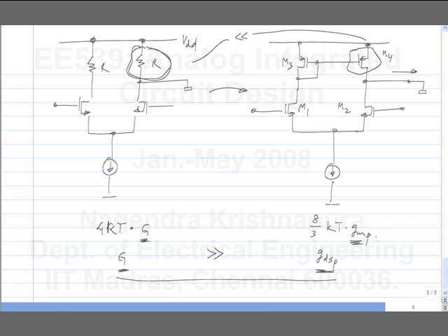So you can realize very high small signal impedances using a transistor in active region, I mean in the saturation region, but the noise will be much higher than if you used a physical resistor of the same value. Is this idea clear? So the noise of this is much more than this, although the conductance is much lower.